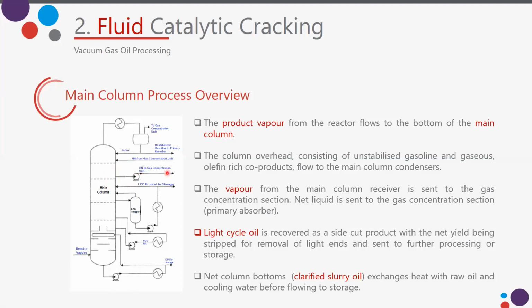It only gives some heat and comes back to the unit. Yeah, so this is the same idea of pump around in the fluid distillation unit. So this is distillation column. Yes. So it provides cooling to the top, plus it improves your fractionation in the main fractionator.